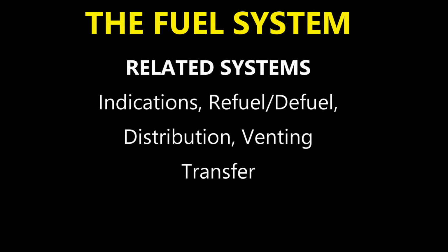As far as operation goes with the refuel defuel system, at what pressure does it need to be at the couplings? It's 50 psi. Because when we have that, we have an average flow rate that we can determine in order to fill the tanks from empty to capacity within a certain time frame. We want a flow rate, so how many gallons per minute can we get?